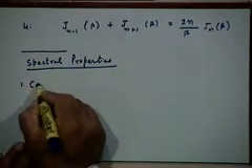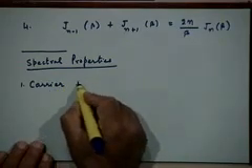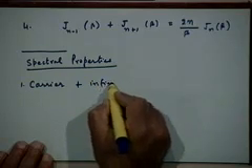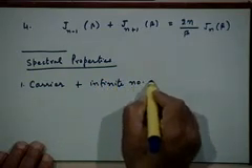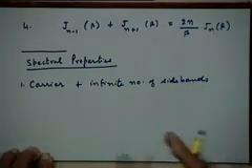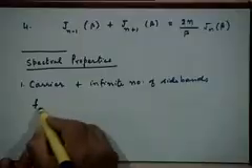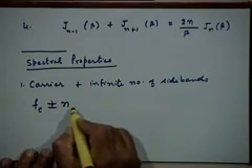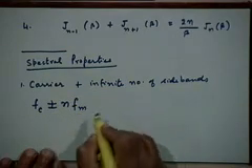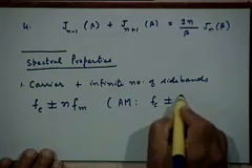First point, we see that the spectrum contains the carrier in general plus an infinite number of sidebands, right, not just two sidebands like we had earlier, both on the positive side as well as on the negative side with respect to Fc. By infinite number of sidebands I mean frequency components like Fc plus minus n Fm, unlike for the case of AM where we had only Fc plus minus Fm.